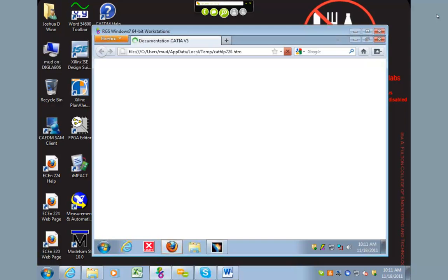We'll go ahead and repeat it two more times to basically get this thing set up. So we'll do another Revolute joint. We don't need to create a new mechanism, but we could if we wanted to. And then you go ahead and click on line 1. There's the first one. There's the second one. And then for this one, let's have this face be on top of this face. So there's our second joint. Same mechanism. Yep. So they're all in one mechanism. So the mechanism name should already be there. If you missed that step, just click new mechanism, and it'll allow you to create a name the first time, and then each time it should already have mechanism 1 as the default.